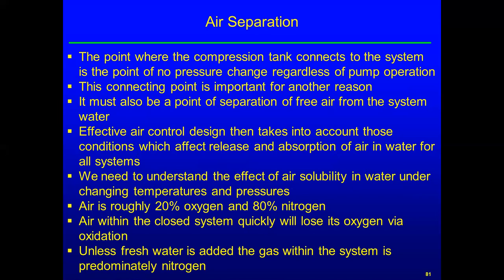It's also the point of separation of free air from the system. So we want any air bubbles to go into an air separator there, and so they can be vented to the compression tank, or in an oxygen-free system to the automatic air vent, and be purged from the system.